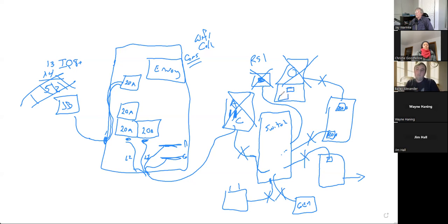And then typically there are going to be like 4 breakers underneath, 4 double pole breakers. And that's what your new electric meter box is going to look like. So instead of the guys coming in and pulling the meter, they're just going to open that up and turn off that breaker. And that becomes the main breaker for the house.